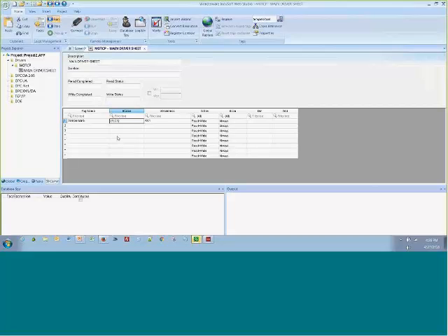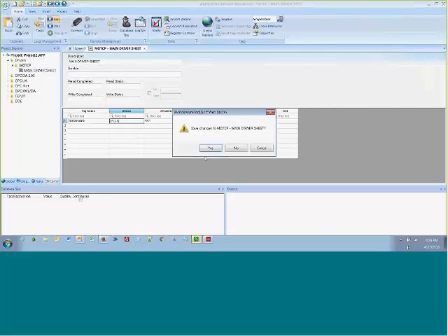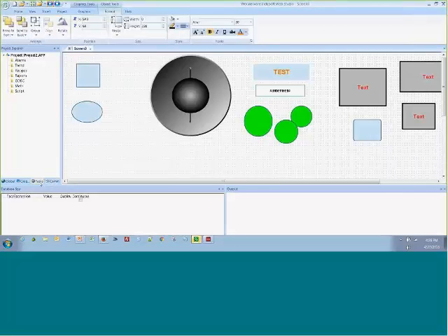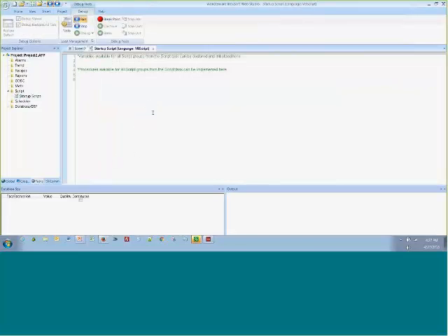But I don't have that PLC1 configured yet. So what I'm going to do is save this, and then in the Tasks tab, under the startup script, I'm going to define that PLC1 tag. In the VB script interface, I need to precede an InduSoft tag with a $, and here you can see that the IntelliSense has found it, and it found that it's a string type tag.